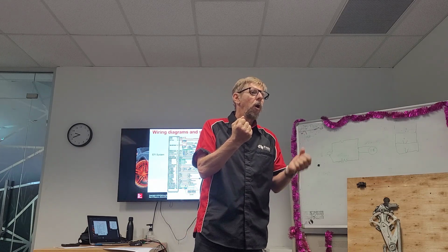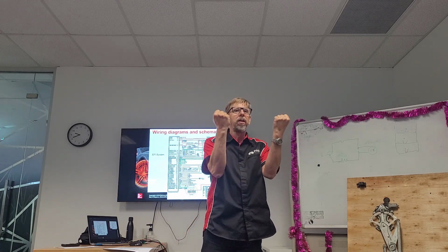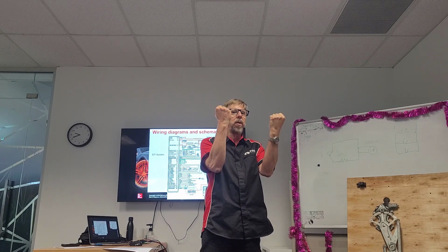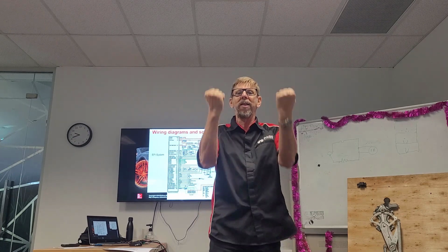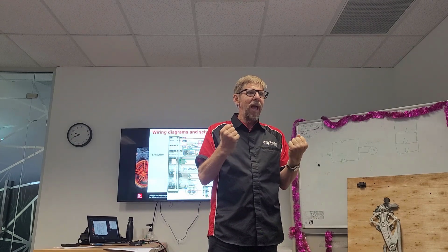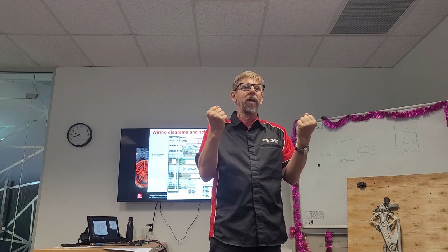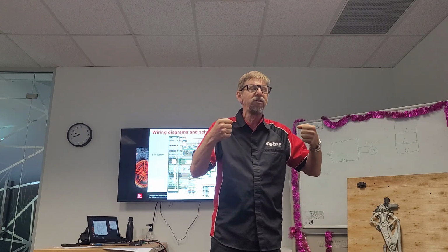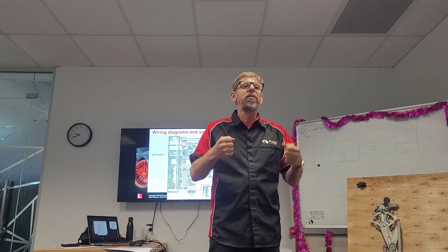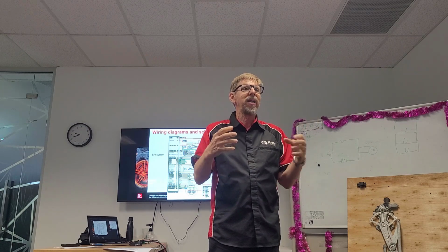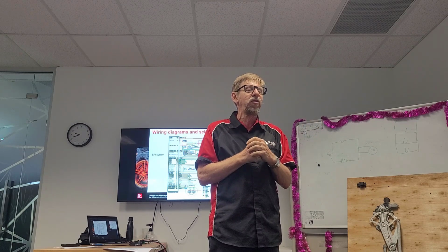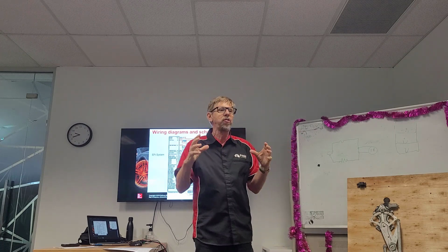Waste spark ignition coils are coils that spark together. So when you're on compression or exhaust, they're sparking together. Even though you might be on a compression stroke, you've got companion cylinders that work together, pistons going up and down. One will be on compression, one will be on exhaust, but they work together. So they spark together. That's what a distributorless ignition system had, waste spark coils.